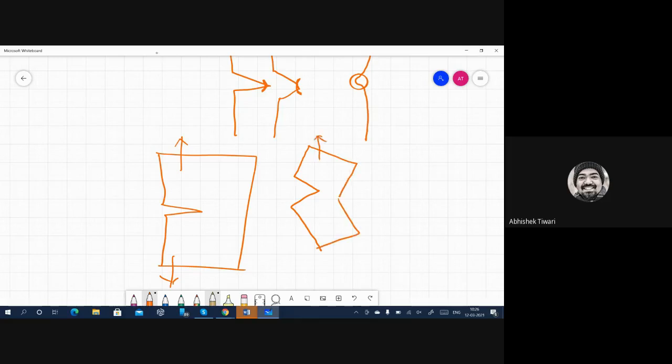And I'm still pulling straight, but this thing, because of its geometry, is going in bending. So you have compression here on the backside. This compression is causing the material to be pushed, and that material is coming at the crack tip. So this is what is happening. And these two material flows can be described in terms of constraint.